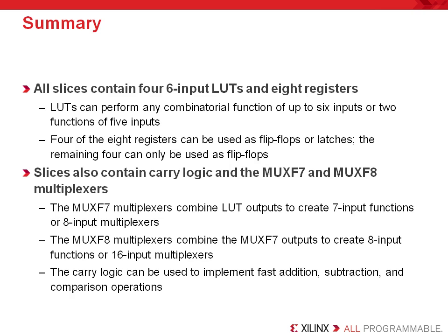In summary, all slices contain 4 6-input LUTs and 8 registers. LUTs can perform any combinatorial function of up to 6 inputs or 2 functions of up to 5 inputs. 4 of the 8 registers can be used as flip-flops or latches. The remaining 4 can only be used as flip-flops. Now, the LUTs and register structures we've seen are designed to give you high performance as well as high device utilization, which also explains why they have so much flexibility.